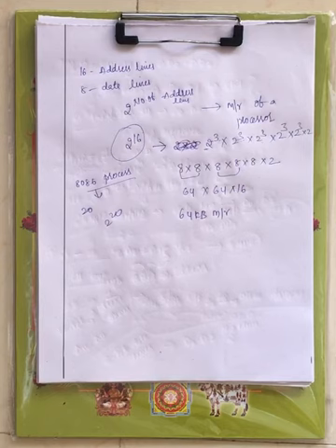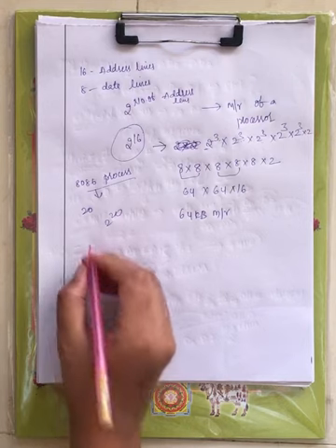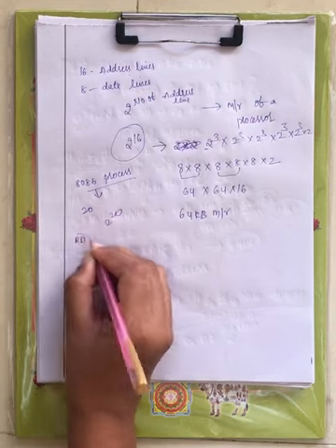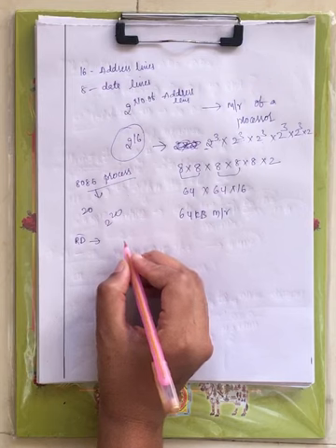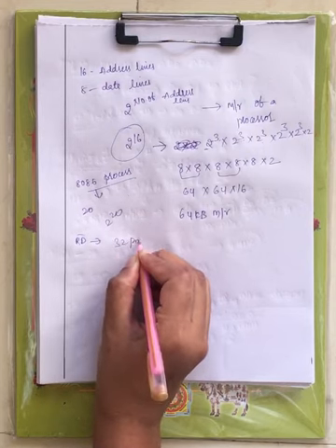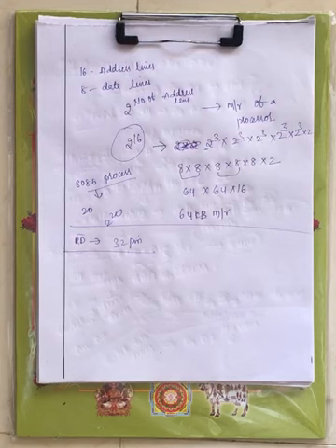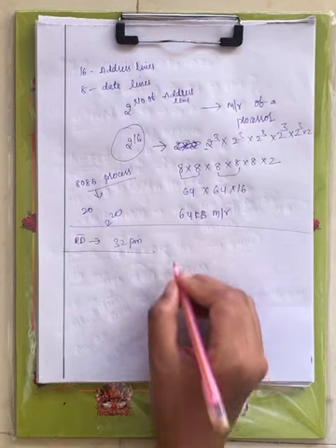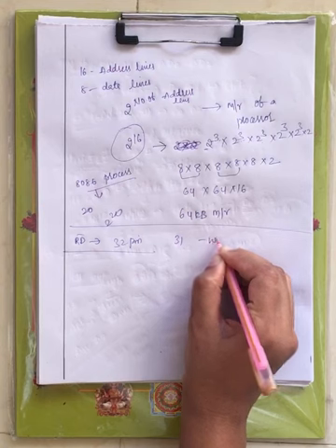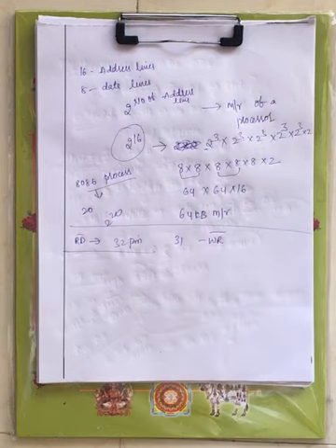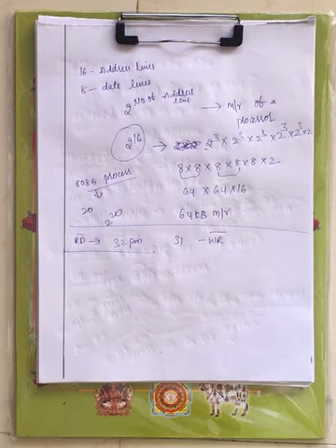That is about the address lines, and we have seen ALE also. Next let us see RD bar, which is provided at pin 32. At pin 32 we have the RD bar signal, which is the read signal, and at pin 31 we have WR bar, the write signal.